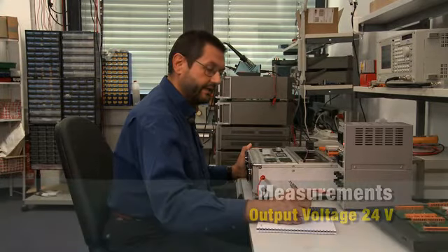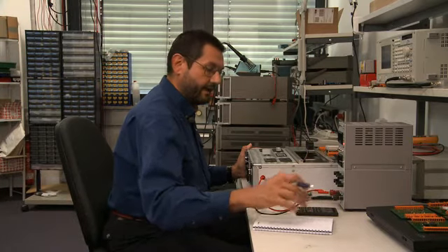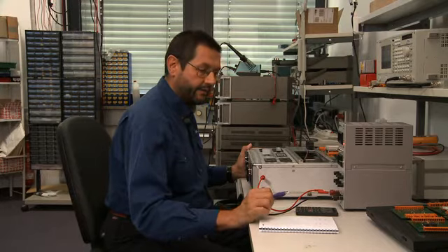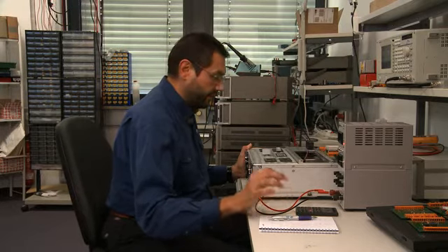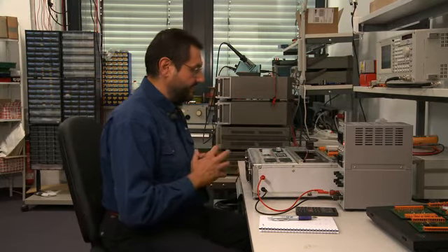So in this way we can easily calculate the input power and the output power and get our power difference, which is the power dissipated by the module. So at this point, we can leave the system as it is and wait for a while until the conditions stabilize and the temperature increase will reach its final value.